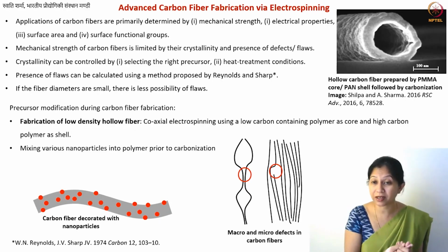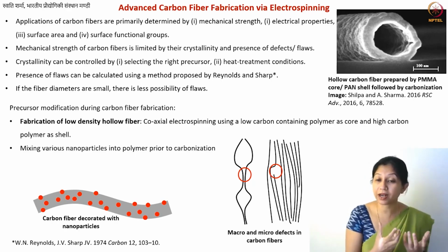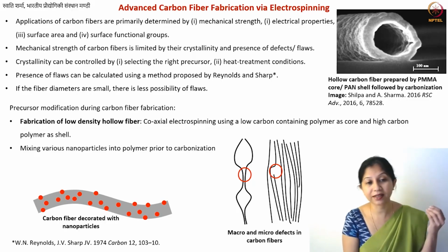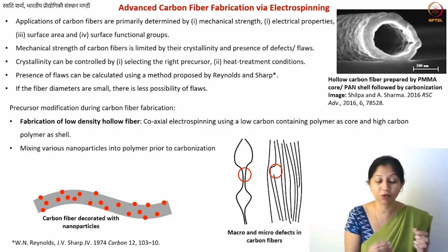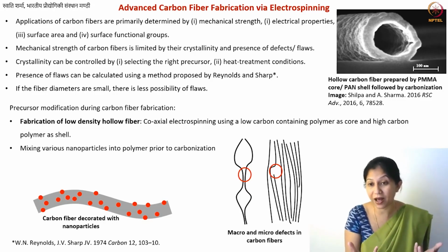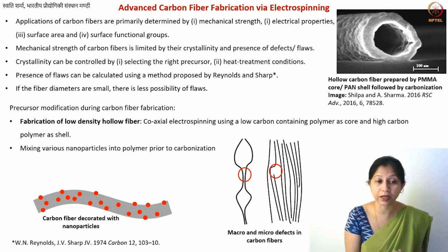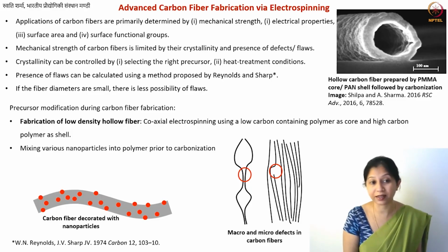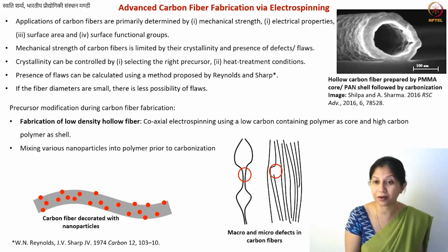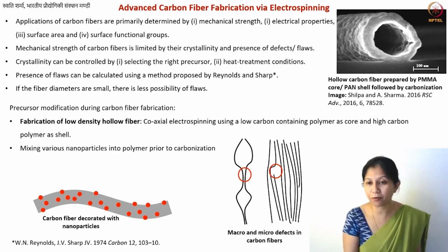So carbon fibers are conductive. If you have a high heat treatment temperature, then you can have conductive carbon fibers. Now you can pass current through these fibers, and you can even perform Joule heating, because if you can pass current through a certain fiber, then you can heat it also by Joule heating. So in that case, maybe at a certain temperature, your nanoparticles become activated. Those nanoparticles can then perform sensing of different types, for a number of biological applications.